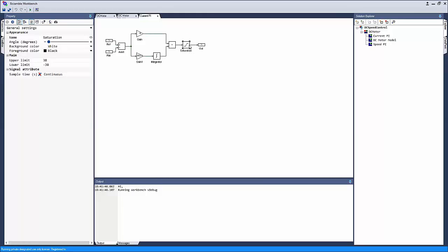In simulation, this control voltage can vary to any value, but we will use a similar model in real time as well, where there is a limited voltage that can be generated. We will use a DC bus voltage of 40 volts in our real world application. We are going to use an inverter which has a bootstrap capacitor, which means we cannot get an absolute 40 volts at the output. There's going to be a minimum dead time required for the bootstrap circuitry to work, which is going to limit the amount of voltage that can be generated at the output. In addition, the switch is also going to have some voltage drop, so that further reduces the amount of voltage that we can practically generate in the actual inverter that we are going to be using next. So we are going to set the saturation at plus or minus 38 volts.